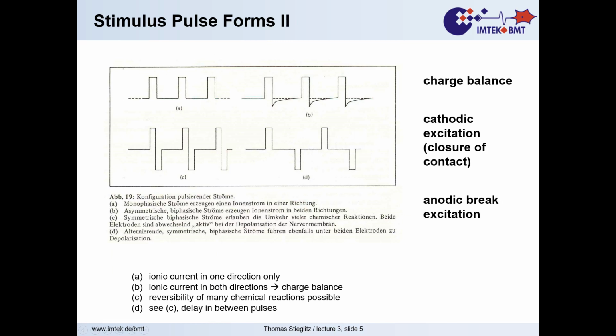What we will use at the very end is something like that. That is a symmetric pulse. In many cases, we have it rectangular. That's easy to implement with both analog and digital circuitry: on, wait, off, reverse charge, on, off, and then wait for a certain period of time. And the area under the curve is the same in the positive and the negative pulse. That means we have a charge balance. We push as much charge in as we pull out. And in an ideal world, if we do that, same in, then out, nothing is left.